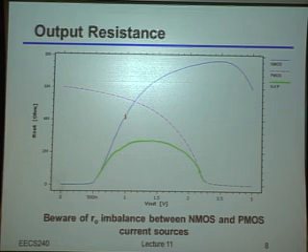So again, the real key point here is that only if you plot those two independently will you be able to tell which one of them is really dominating the overall swing range, if either one of them actually is. Because if I look at the parallel combination, especially in the differential context, it'll be totally symmetric. And you wouldn't be able to tell if, as the swing is coming down, the NMOS is crapping out too early, or as the swing is coming up, the PMOS is crapping out too early relative to what you would want it to maintain.